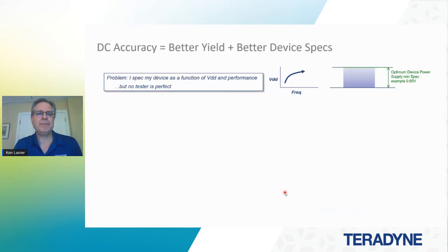The first is what happens statically. Now, when they sell processors, there's usually some balance between the VDD and either the frequency the device will run at, the number of cores that will run, things like that. So when these devices are sold, you usually try to find a sweet spot where the device will do enough work to be useful, and it will be at a point in the VDD curve where it's not drawing inordinate amounts of power. So if you're in a mobile device, for example, this VDD actually changes over time and adapts to what the processor has to do.